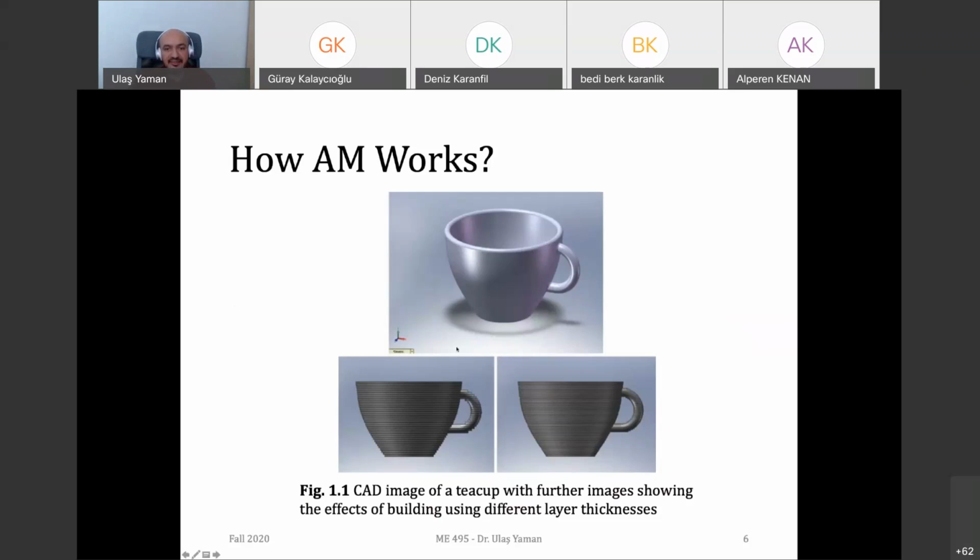So in summary, you design it in CAD software and import it into the manufacturing software, like your friends pointed out there. Cura is one of them, and each printer company has its own software, but Cura is the most popular one for deposition modeling. In that software, you do some settings, play with infill parameters, layer thickness, and try to increase the quality of your overall product. And finally, you submit these generated commands, the trajectory of the head of the printer, in some different formats to your printer, to your additive manufacturing machinery, and then start the fabrication.